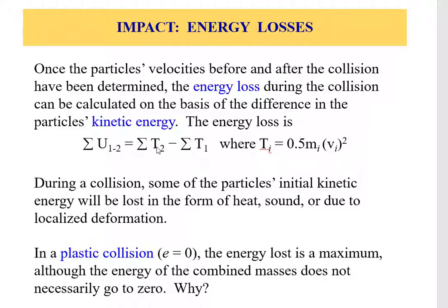So we can compute the energy loss by the difference in the kinetic energies. At best this is zero when there is no losses, which is nearly impossible. And the maximum energy loss happens, as we said, in the plastic collision when the two bodies stick together, but it is not necessarily equal to zero.